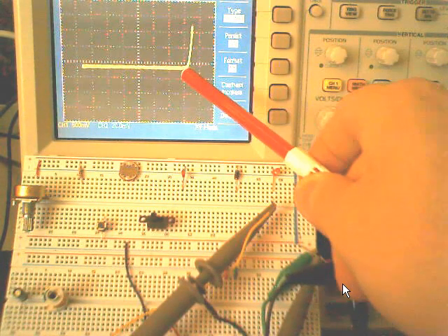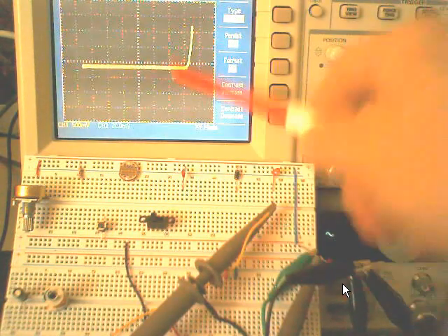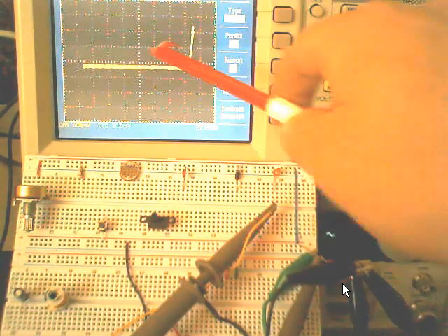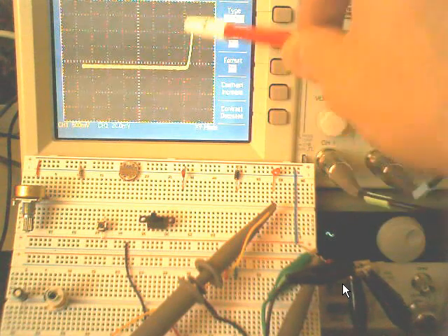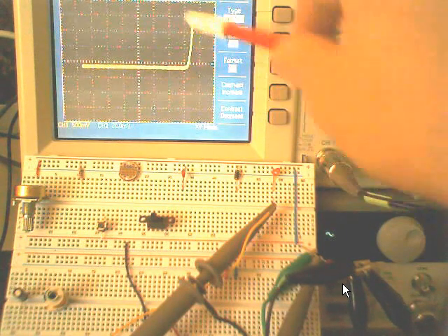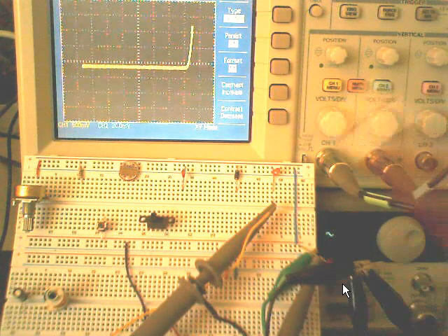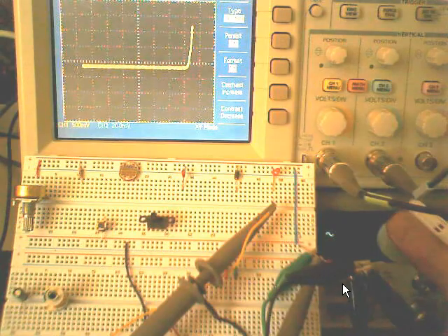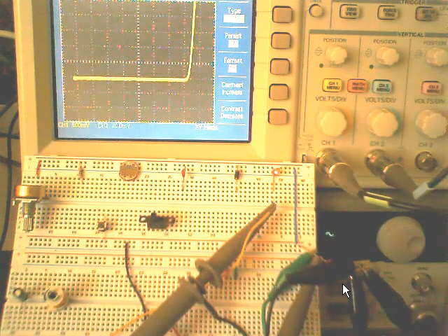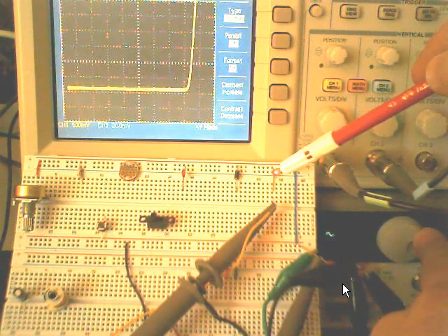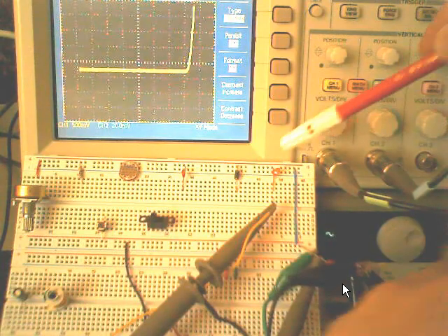You see that for voltages smaller than some threshold, there is no current. It's high impedance, approximately open circuit. But when I exceed some threshold voltage, there is a current, and as you see, it has a very small resistance. And as you see, this diode emits light. Look carefully, please. Can you see the change of light of this light emitting diode? Look, it's changing. Its brightness is changing. It's emitting light.